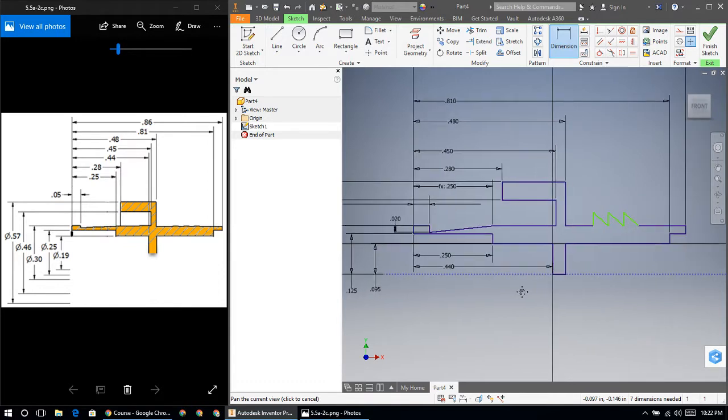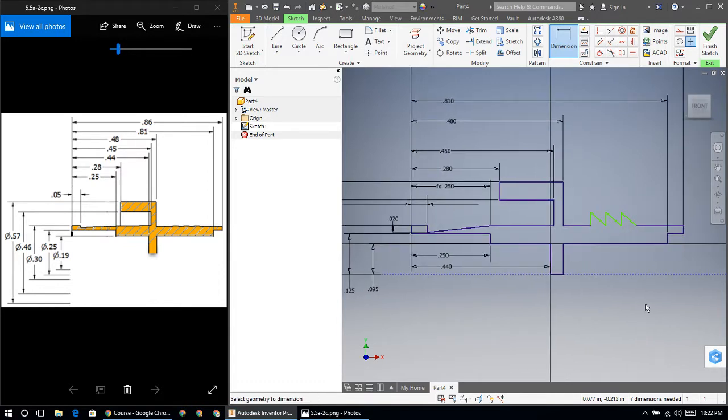Now that line's locked in blue. And the last thing that I have are these 3 triangular shapes here. And I'll tell you right now, to put those in place, we need to know how we're going to start on our right edge, and from that end point to this point, the right point of the first one is going to be 0.1. And then each one of these from here to the next point is 0.6.